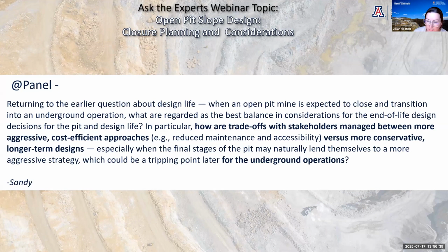So we have that. One quick example, from a couple of projects I've done: when you had an open pit and you wanted to close it as a pit lake, and then they've gone underground, if the underground access is from downslope and you maintain the hydraulic connection between the pit and the underground, then you're left with a decision of whether to leave the pit dry and drain it all out through the underground, or whether to plug the underground and flood the underground and the pit.